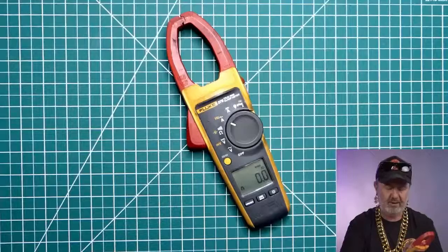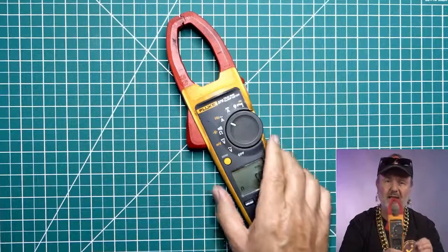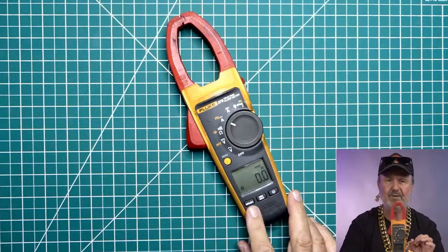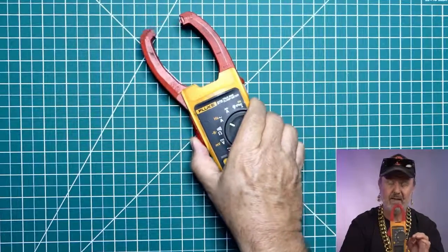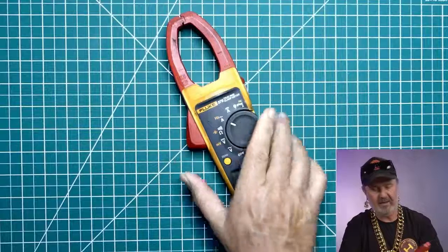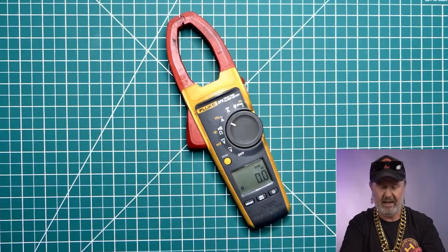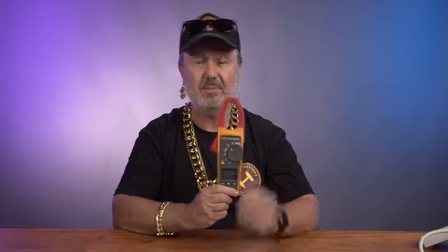And if I press the inrush button, in fact, why don't I turn it on for you? If I press the inrush button, it will sit there waiting until it measures a peak and then capture it for me. Now, this is a very short peak, and it's in amps. So I can find out, well, volts as well, but I'm going to put it on amp range, and I put on AC amps because I'm measuring an AC appliance, but it can also measure inrush on DC if you need to. But for our purposes, we're concerned about mostly AC appliances in a home these days, and you're looking at the inrush on the active conductor. So that will be generally measured at the switchboard. So that's a peak that's really useful.